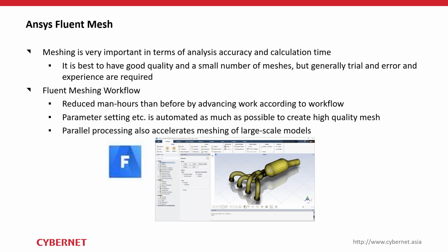Meshing something appropriately is very important in terms of getting accurate results for your analysis, and also in taking care of the calculation time. I mean, you can mesh your model with the finest mesh available, but then it will take a very long time to solve the problem.